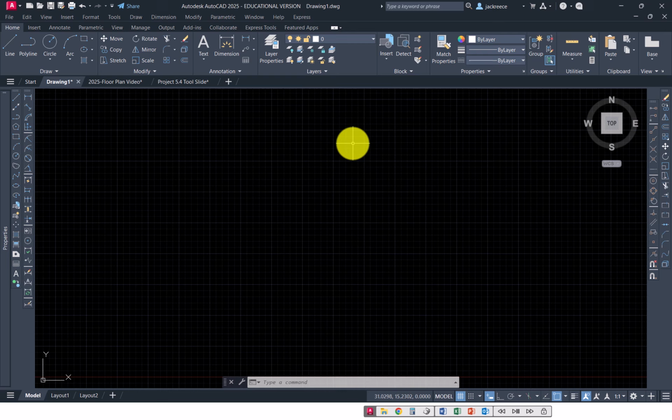We create a block, and then we can just insert it into our drawing. When you create blocks, you create the block on layer 0, and when it's inserted into your drawing, it inherits whatever layer is current when you insert it. That's why I encourage you not to draw on layer 0 once we start creating layers in this class.